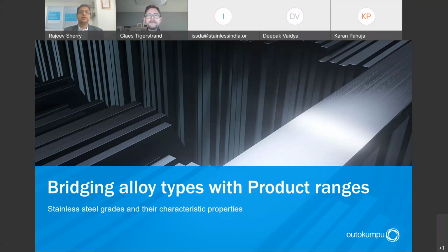So class, what is the right answer, and can you give some explanation? Yeah, it's a bit tricky. We will actually come back to it, but I mentioned when we were talking about the alloying elements, which are austenite stabilizers, and the most important one there is nickel. So normally you will not add nickel to a ferritic grade, where you will instead go for the ferrite stabilizers like higher chromium or molybdenum content. So nickel is the correct answer.